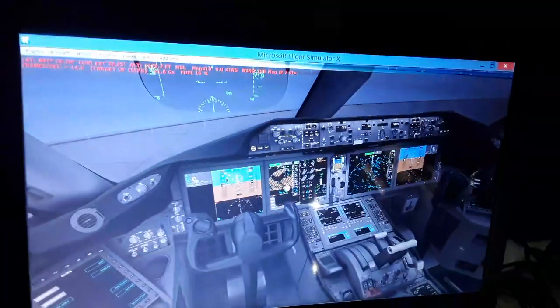As usual, we're gonna calculate where the fuel is stored and how much we have, 30% in the left and the right wing tank and 10% in the center tank. It's gonna calculate also the loads from the passengers and cargo. Also, as we fly, the aircraft is gonna burn fuel, and this is gonna shift the center of gravity in flight. It's gonna recalculate it automatically every second as we fly.